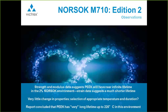And I would probably conclude also that overall the results are rather unreliable and are not very useful for predicting long-term performance of a high-temperature, thermally stable polymer such as PEEK. So I guess I'd need to ask myself then if the temperatures and aging durations which I had chosen were sufficient in this case. And hindsight is a wonderful thing, and with hindsight, my opinion would be no, I had chosen the wrong test parameters.